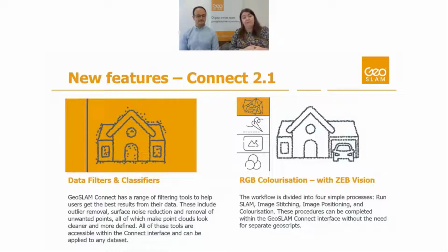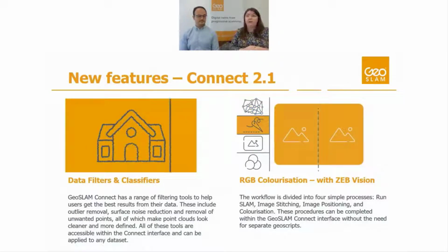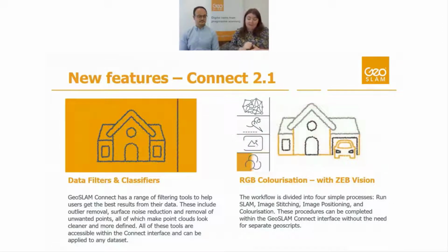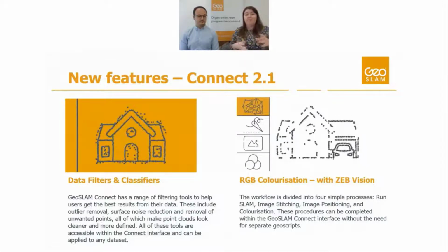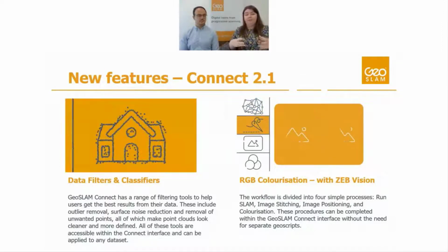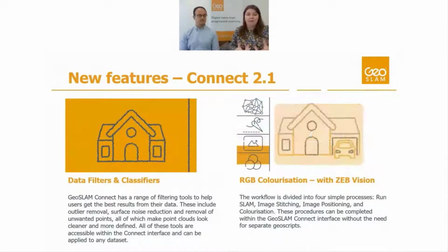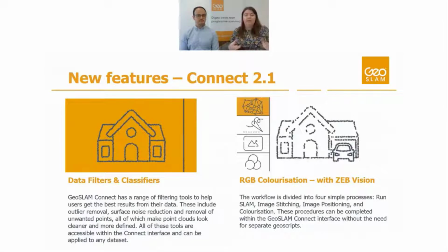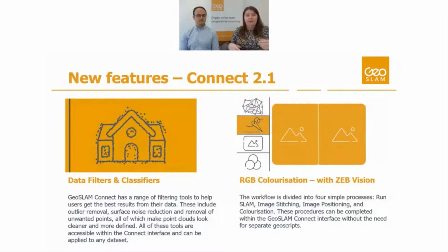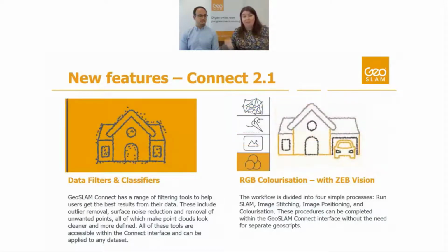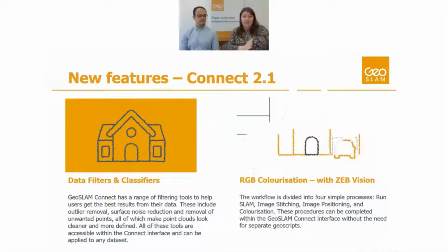And then we have a transient filter as well. The transient filter is sometimes known as a moving objects filter. It's not a people filter, so it won't filter out specifically people, it won't be like an object classifier, but it sees clusters of points within an environment. If they are stationary, such as walls or buildings and things like that, then they will stay.